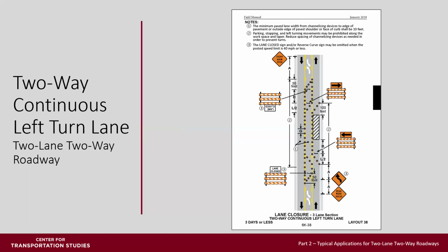An option that you have with this roadway is, again, similar to the previous example, where you can still maintain 2-way traffic in that section while working in one of the lanes by shifting traffic over into that left turn lane. Again, you might want to consider using restricted turns through that area so people aren't turning in through your workspace or across a lane of traffic.